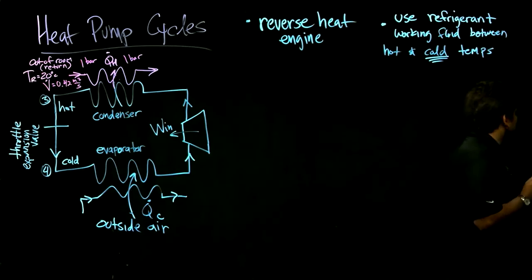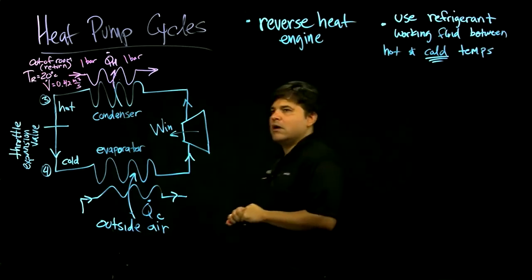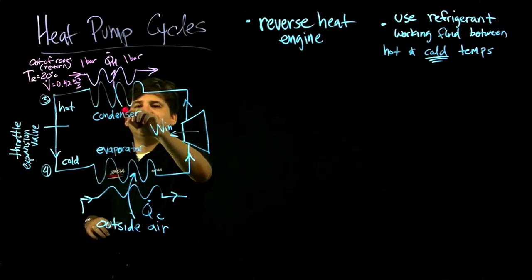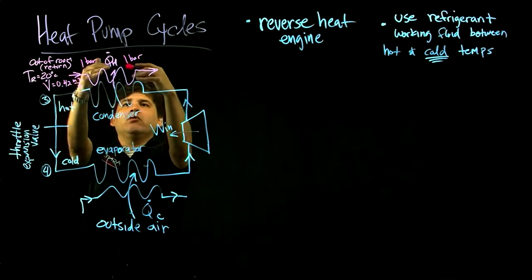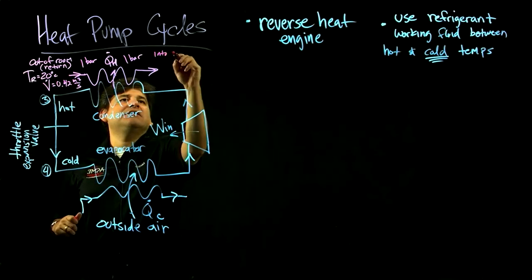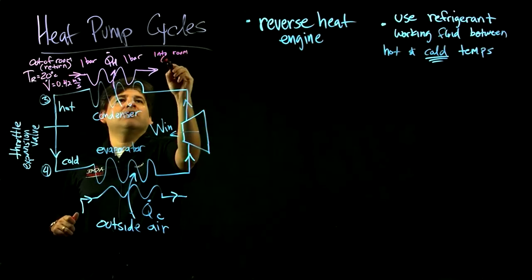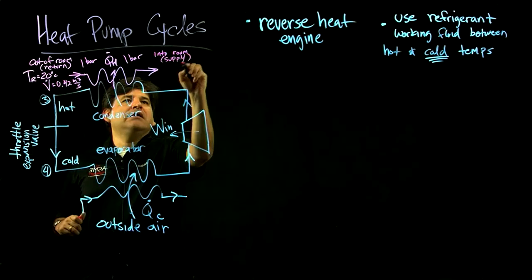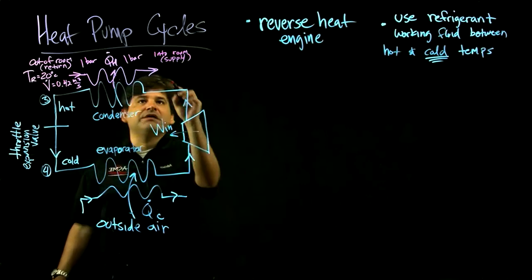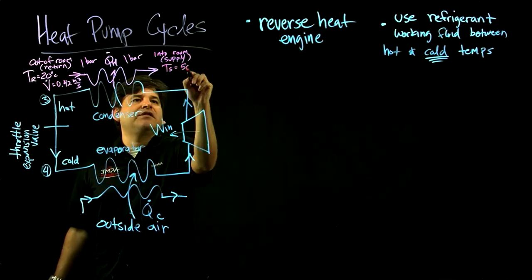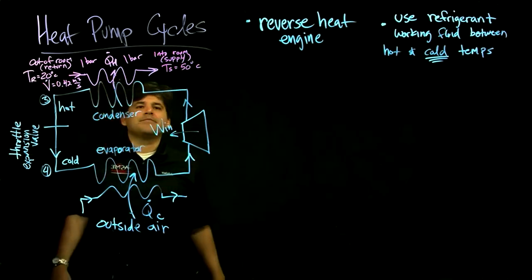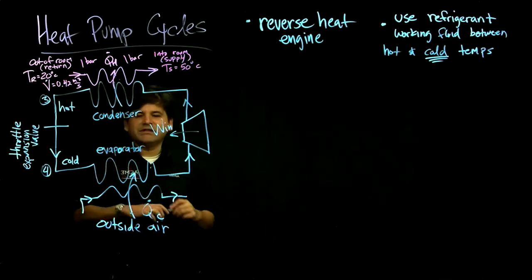We are using this heat pump to keep a room warm by heat transfer at this condenser stage from the refrigerant to the room. And after this heating process, it goes into the room, which is called supply in HVAC MPE terms. And let's say that this temperature of the supply is now 50 degrees Celsius, which is pretty good. Still isobaric. Okay, so this is the application.